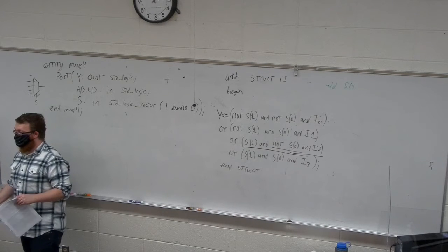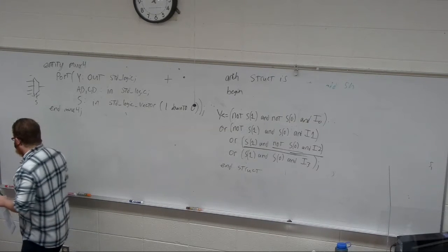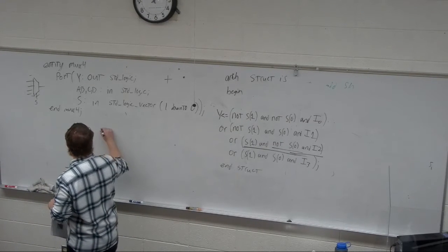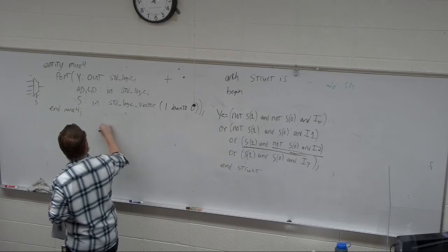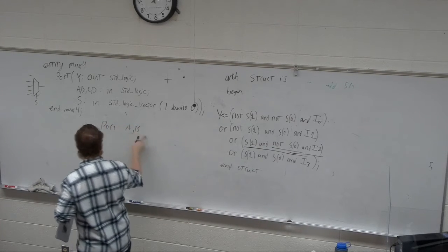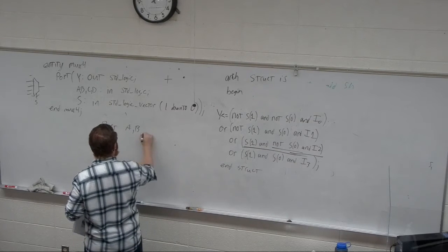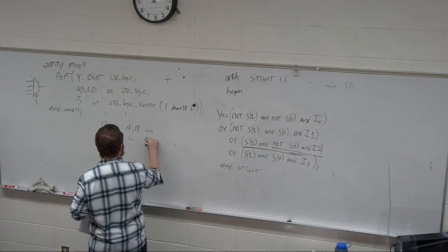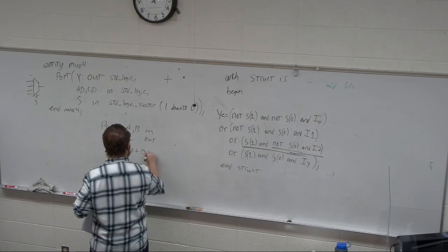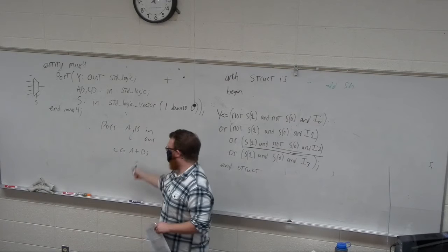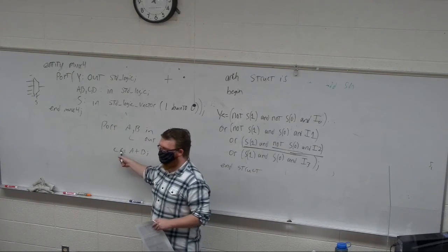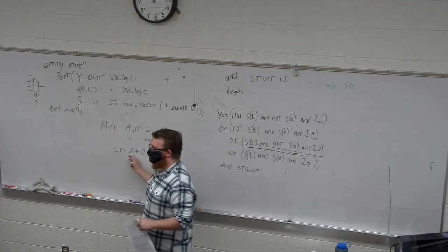You can also be a little bit more arbitrary, and as long as you use the correct types, an adder would just be, I'm going to pseudocode this: I have ports A and B that are inputs, and I have a C that's an output, and then I just say C is equal to A plus B. Done. I just made an adder, right? This is a nice thing about VHDL, it allows you to do this, as long as these types are correct.